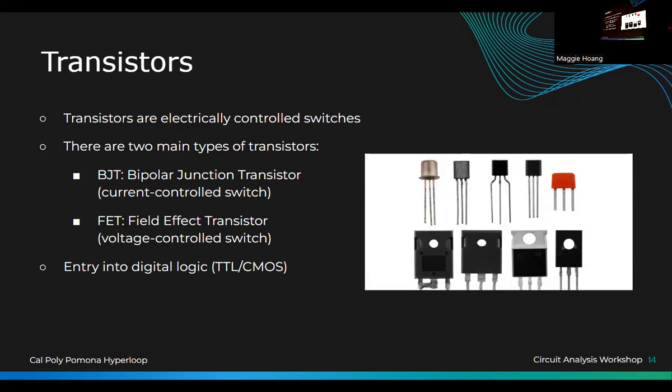Those are digital gates, where you turn binary from 1 to 0, and there are different rules. All those little chips that you use with the AND gates and everything are basically a lot of transistors put together to create those types of gates, right? And then analog people use transistors for amplification. So you could put in a signal that's 5 volts and it becomes 10 volts, depending on how you bias the circuit.